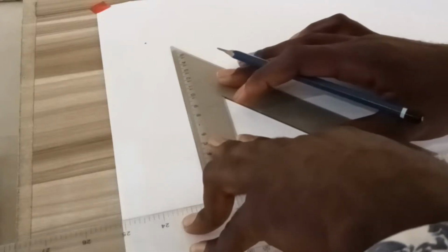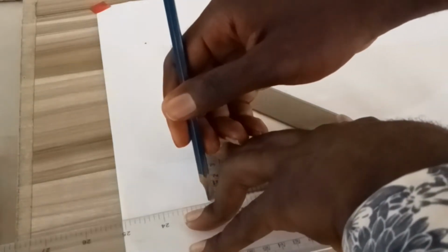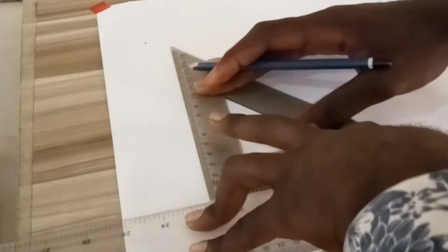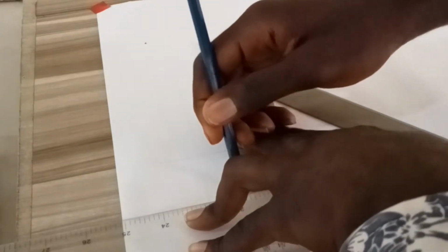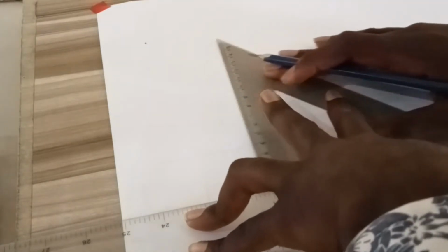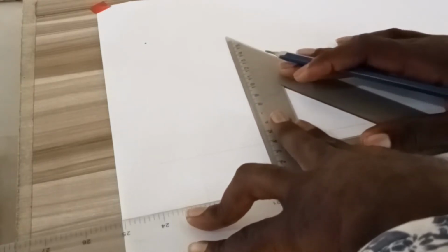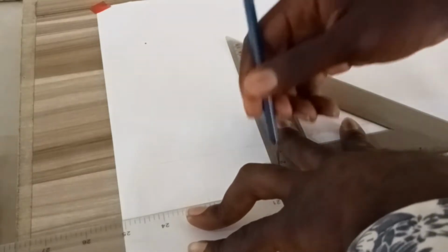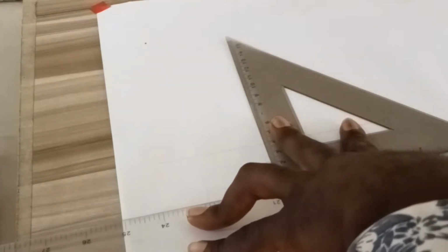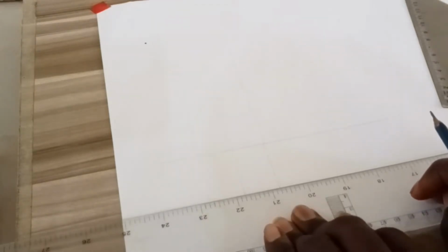So you want to mark out the midpoint of the base, because we need to draw lines through the start, the midpoint and the end of the base. So draw perpendicular lines on the initial horizontal line we drew. Make sure the vertical lines you're drawing are very long, because we need them to draw the entire plan and front elevation.